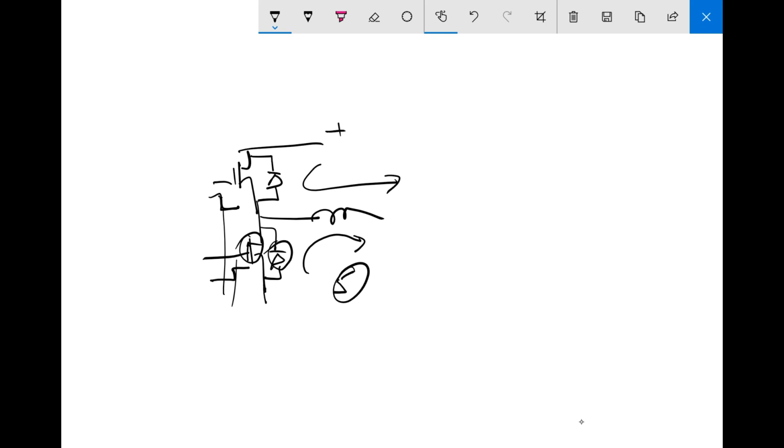Now, the information about the conduction of the transistor in the so-called third quadrant: if this is voltage, this is current, this is the normal, the first quadrant, and here is the third one. This is when the diode or the transistor is in the reverse direction, and this information should also be given, as to what the characteristic of this device is in this mode of operation, which is very important, of course, in all PWM converters.